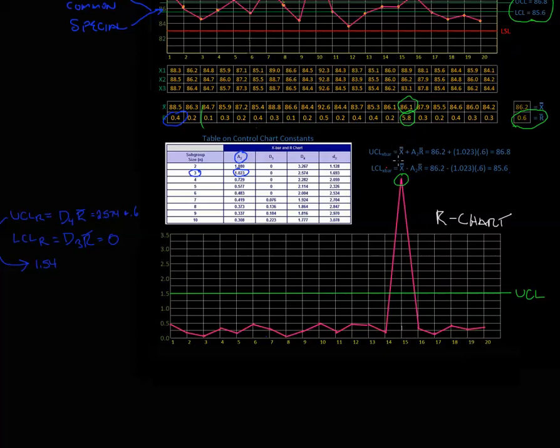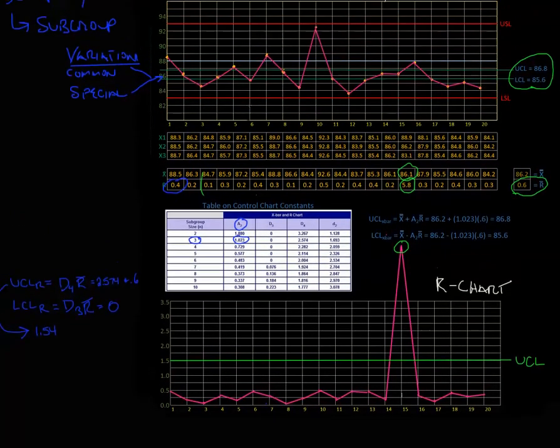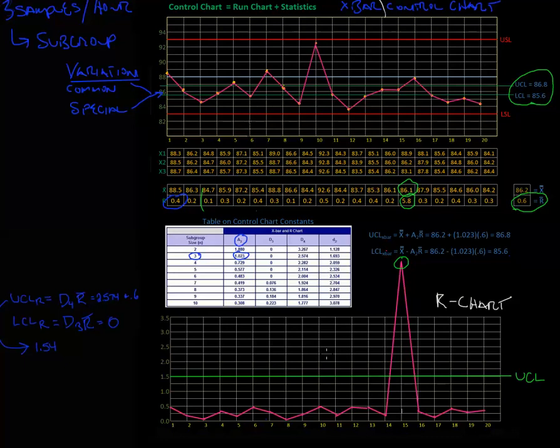One of the first things I would do is look at the measurement system. Look at the samples. Maybe there's a sample preparation problem or something in the lab. Maybe even the samples got confused in the lab with some other samples. There's a problem here that needs to be investigated. So that's the trick. When the process is out of control, you investigate, and there are different ways of looking at our data.